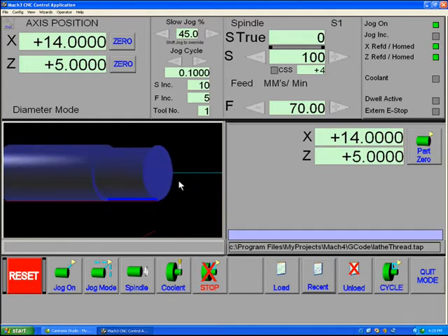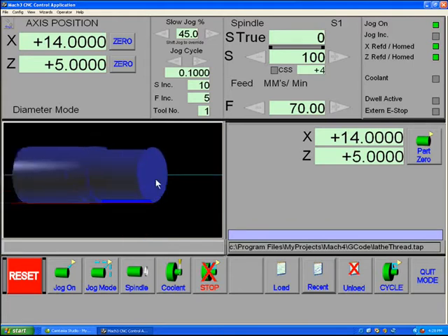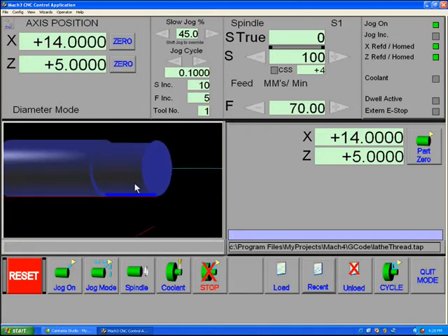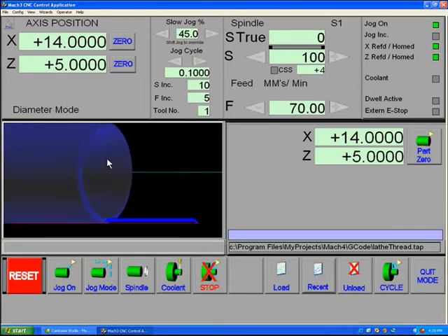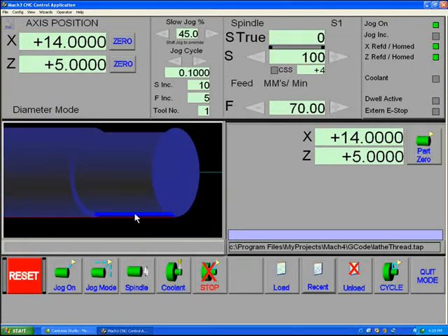That's something that you'll learn through experience as you begin to go. The toolpath display, these 3D shaded objects, try their best to show you what your stock's going to look like. They're not always perfect, and not a great deal of time has been spent in making them completely accurate to the true world. They're really just a quick indicator of what you're doing. And in this particular case, we're doing a threading job, and if we zoom in, you can see parts of the cylinder will disappear when you clip them off the screen. You'll see your cutting job, and this is a standard thread.